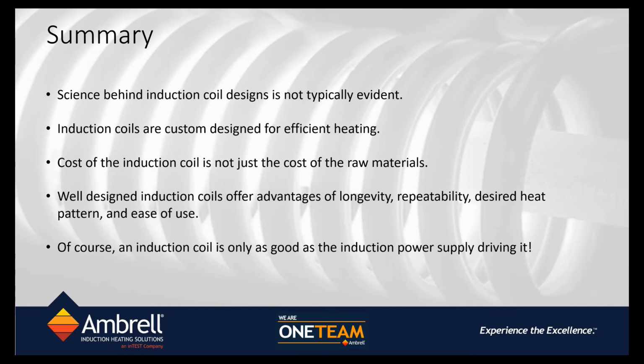So if you just Google or search for levitation heating coils, you'll find that they're designed in a particular manner, because the coil turns are not only used to float the part, but the coil turns are also used to basically not let it just fall off the coil. So the turns of the coil are wound in opposite directions to basically locate the floated part in between the two sections of the coil.